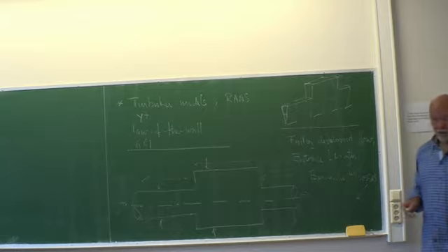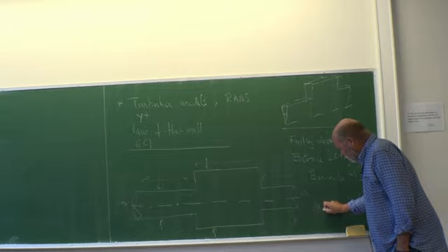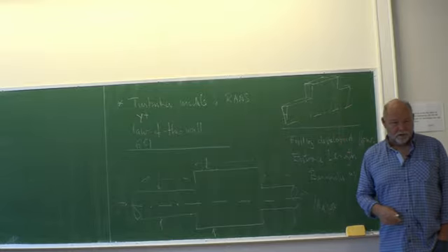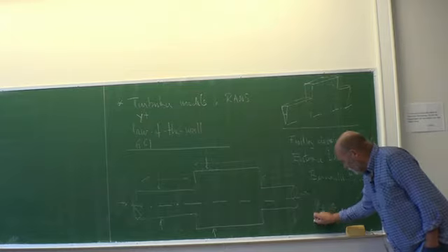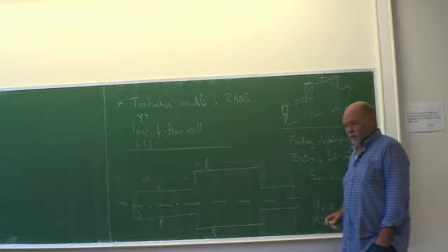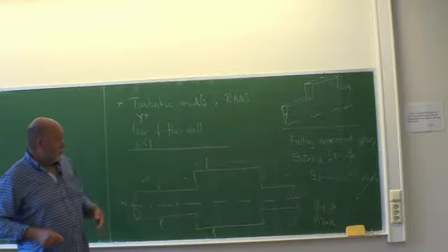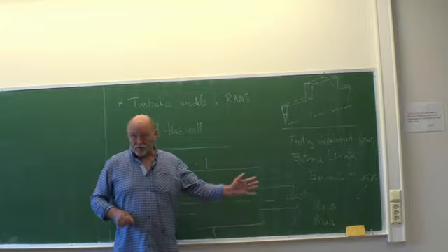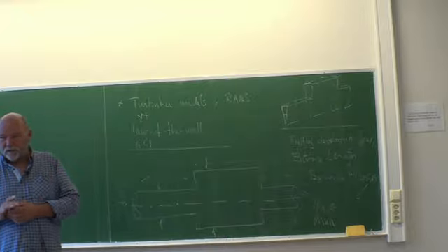And losses, what we did in kindergarten, at least in our university, we split that one in two. You have major losses. What was that? That was the friction, the viscosity. And then you had minor losses. Minor losses, that was losses due to, say, change in geometry. If you have a pipe bend, if you have an expansion, contraction, you had different types of these minor losses.